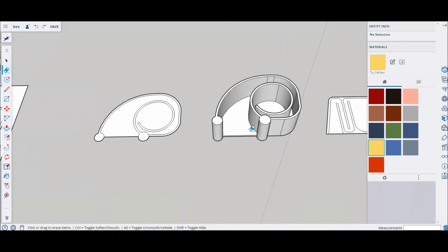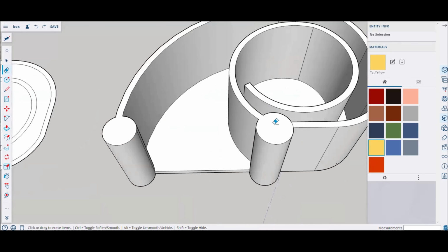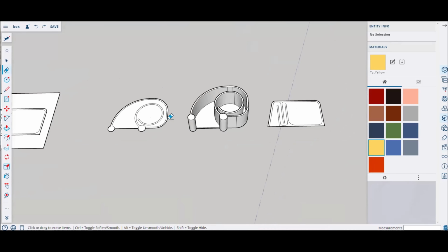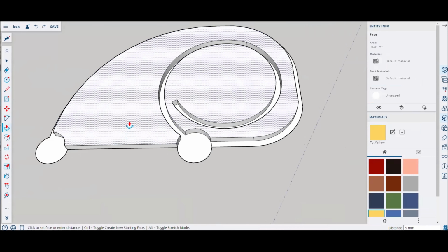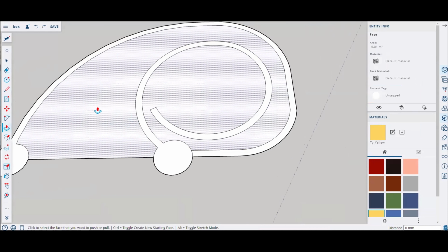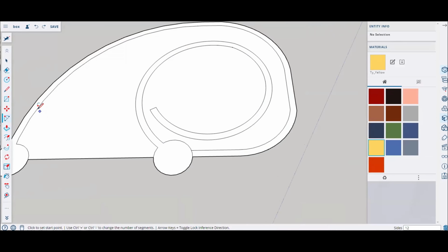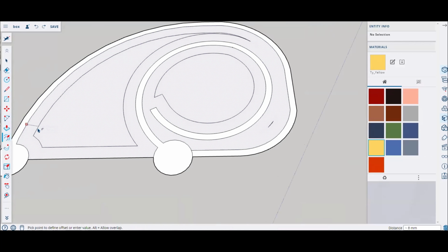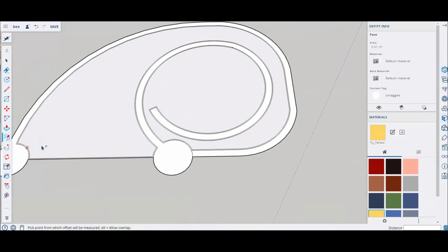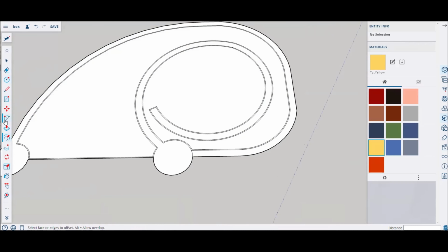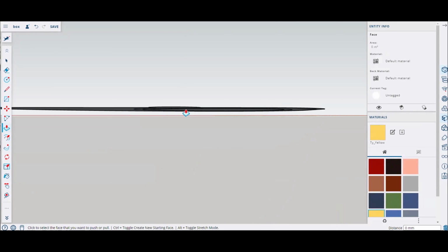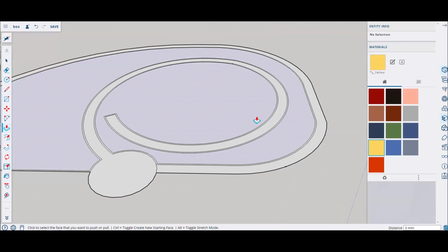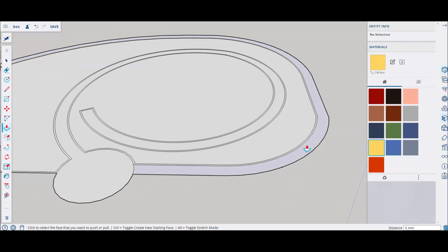Oh, before I do that, I'll show you. Let's say I want to put a lid so that it actually seals up well, not just a plain lid. What I can do is extrude the inside of this where it slides into it, but I just have to allow a little bit of thickness so that it has room to fit in. So I'll come in by 0.5. And then I'll extrude that face, but I have to extrude all of it first, so that it's all got its thickness of 4 mil.